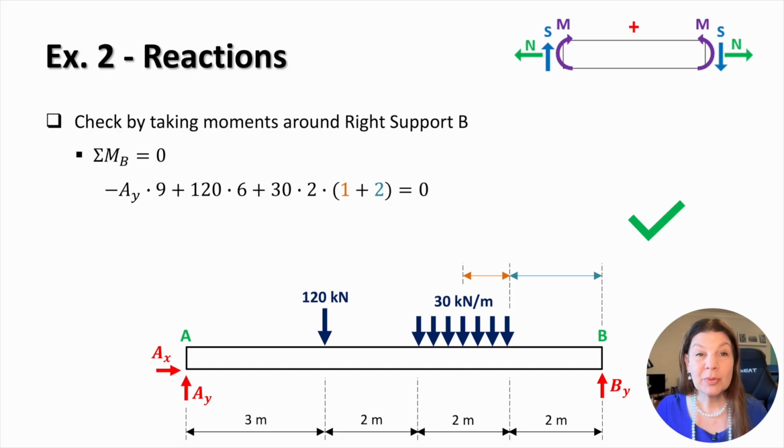And as before, we can verify the reactions by taking moments around support B. If the equilibrium equations are satisfied, the calculated reactions will produce a balanced moment equation, confirming the correctness of the results. Performing this check is good engineering practice.